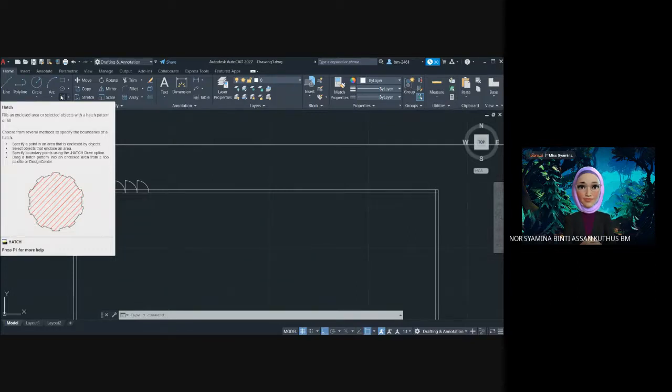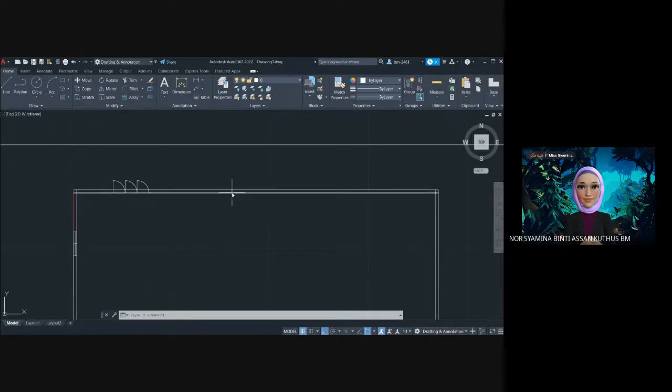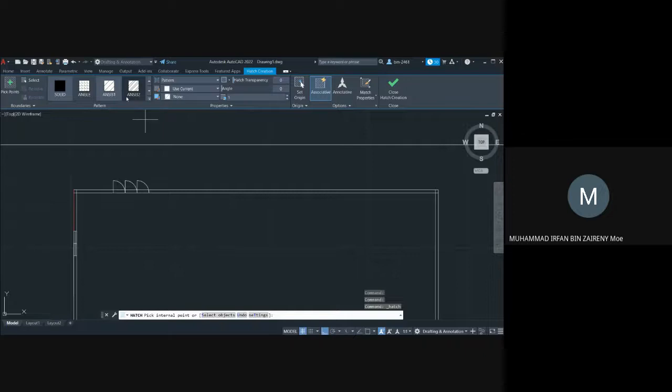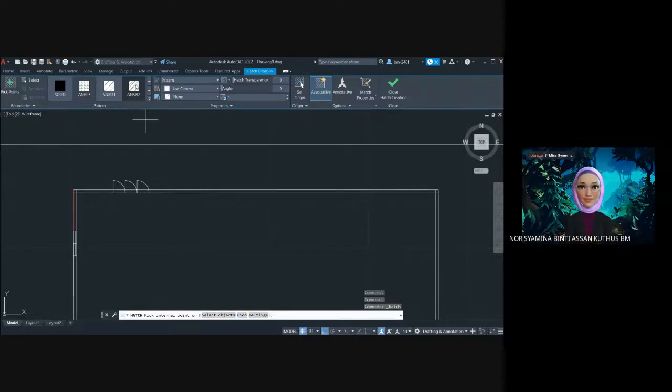Okay, here you can use the information I gave earlier. What are the information that I gave you for wall hatching? He mentioned something earlier, right? What is it? Quickly. For wall hatching, when you click hatch, the types of hatch we want to use will appear. Which one do we choose here? Which one are we going to use? The rightmost. We will use ANSI 32, we will use this, for example, click. And we can change this pattern scale to 10. It was given in the notes earlier, the scale is 10. Enter, and now we can simply go and select.